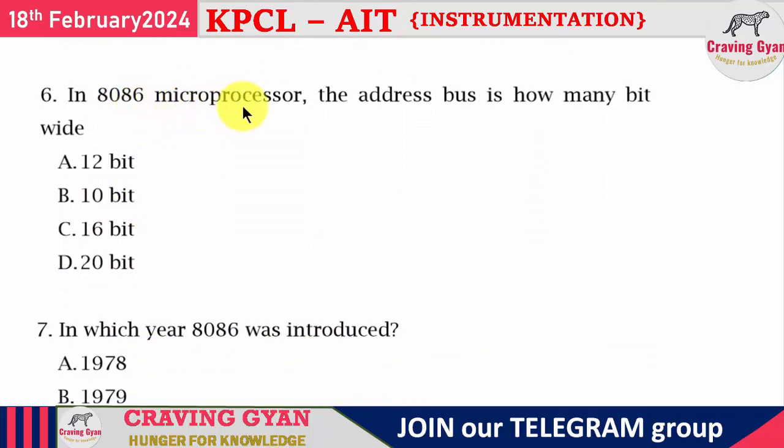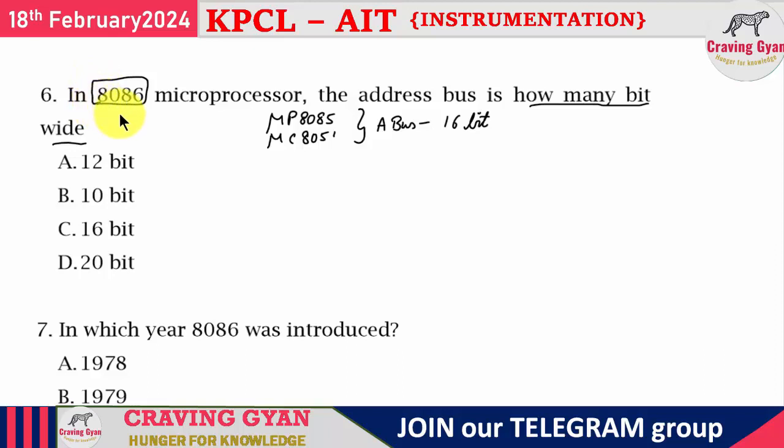Sixth question: in the case of the 8086 microprocessor, the address bus is how many bits wide, they are asking. In the case of microprocessor 8085 and microcontroller 8051, the address bus is 16-bit wide. But in the case of the 8086 microprocessor, the general purpose registers and many other registers are 16-bit wide only, and the segment registers are also 16-bit wide. Now the question is how we generate this 20-bit wide address. That is nothing but how the physical address is calculated.